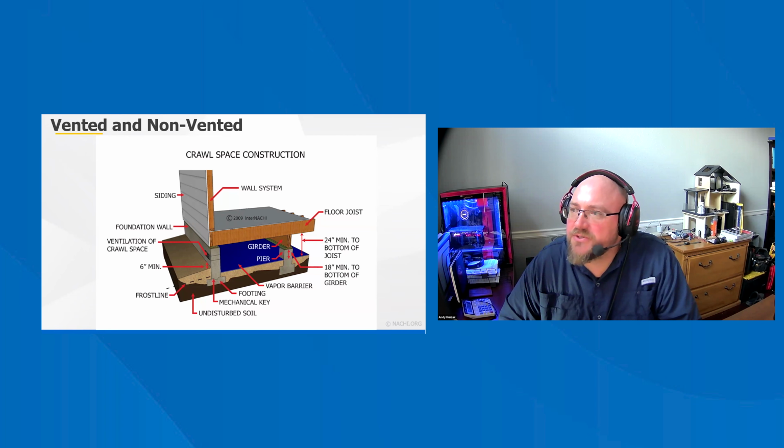Recent model building codes also recommend that non-vented crawl space be treated as conditioned basement space. That is, it's supplied with conditioned air along with a return air transfer grill placed in the floor above the crawl space. Alternatively, the crawl space could be mechanically ventilated or designed as an underfloor space plenum for the distribution of conditioned air. While non-vented crawl space designs without these features have performed well, inspectors should check with local code requirements when inspecting a non-vented crawl space.